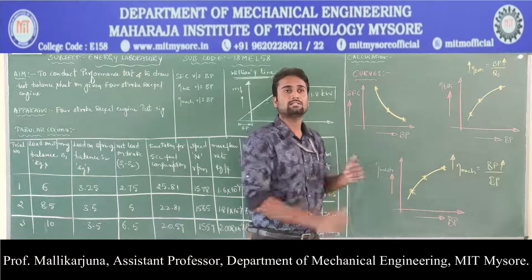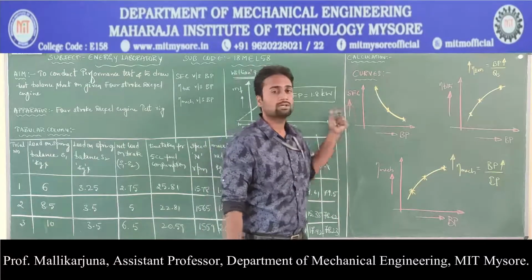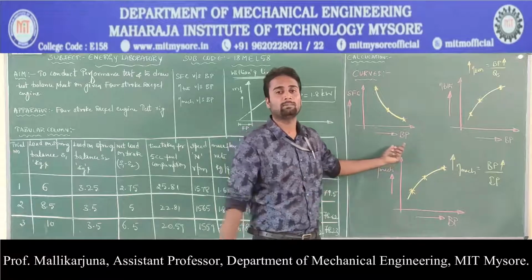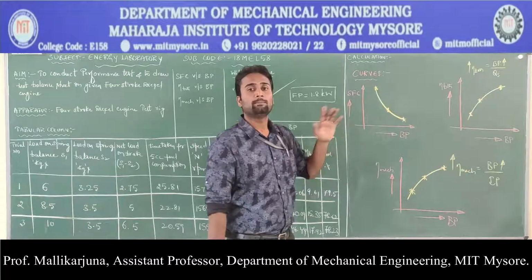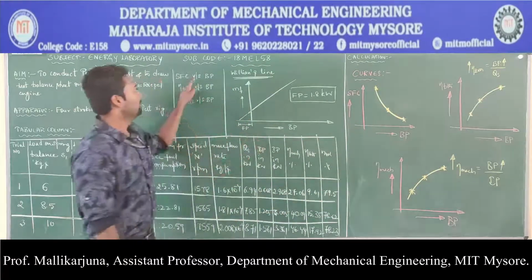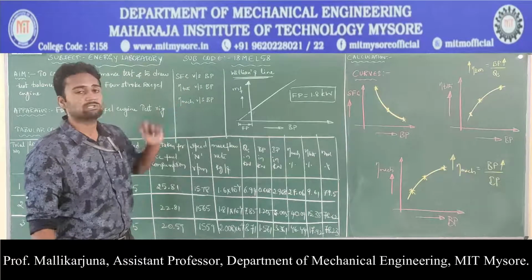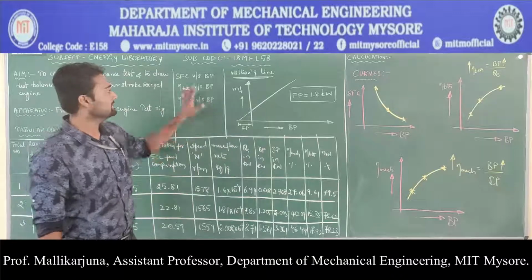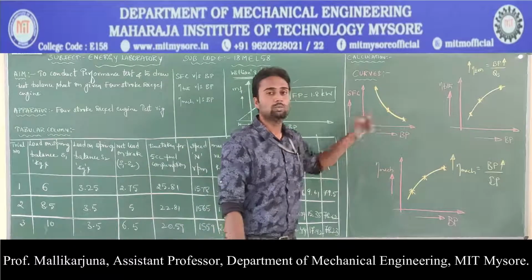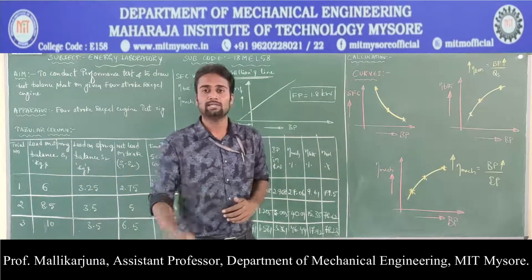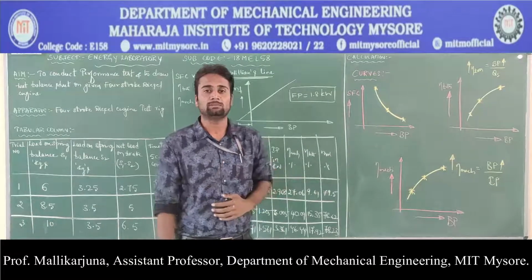As engine runs, as engine reaches its normal temperature and normal operating conditions, the specific fuel consumption per kilowatt development of the power is going to reduce. That means these two are inversely proportional to each other. So very first graph is inverse proportionality, second graph is direct proportionality, third graph is also direct proportionality. So these are the characteristic curves that we were about to plot, and we have looked into those characteristic curves. In the next stage, we have to look for the energy balance that is happening in the engine.